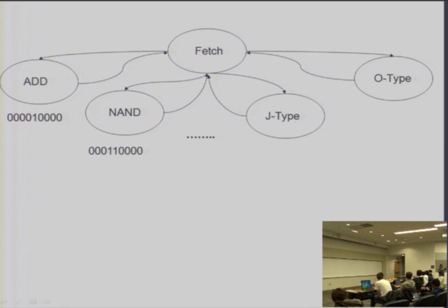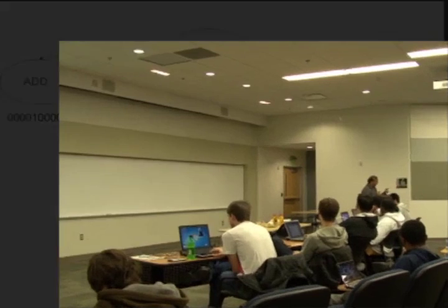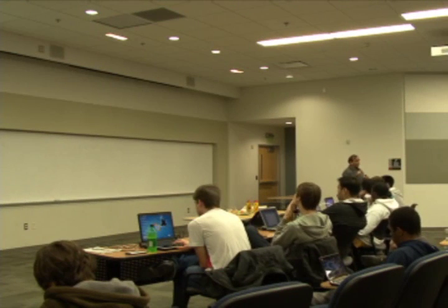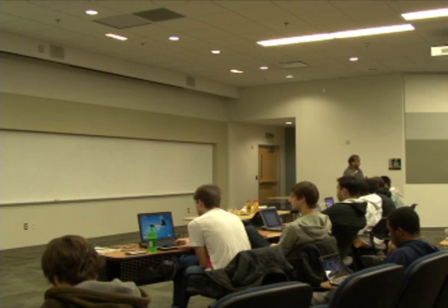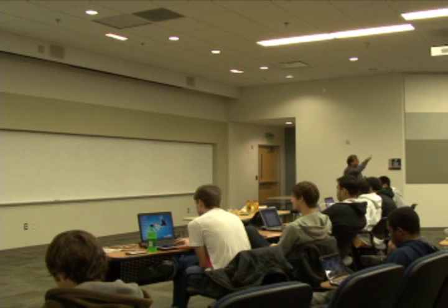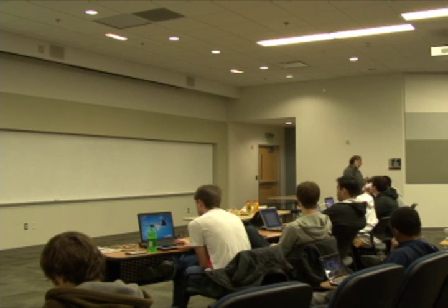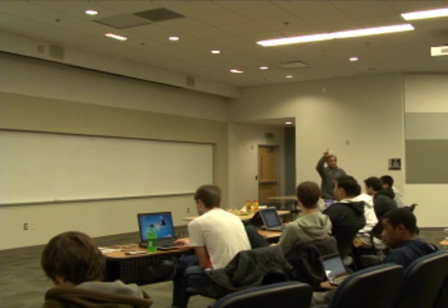We had to go from two different paths back to the fetch. The normal path is you complete the sequence, don't modify the PC, just go back to fetch. The other one is you modify the PC and use a modified PC to go back to fetch.